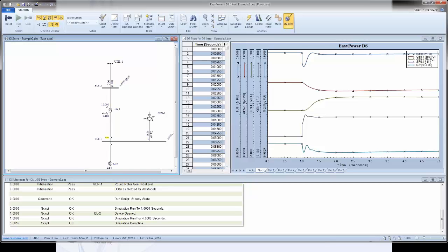The assumption is that the load flow module of EasyPower is going to solve this system for you, give you all the currents, all the voltages, all the power and reactive power, and everything is going to be given out in terms of reports or displayed on the screen. Those are the values after the system completely settles down. In other words, the system will find a steady state point, and that steady state point is what you see as the final result.